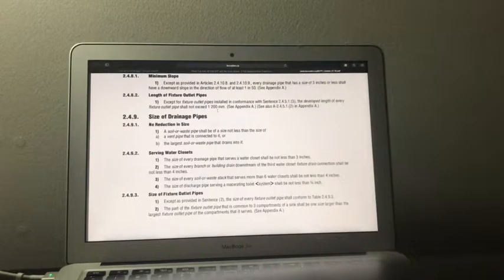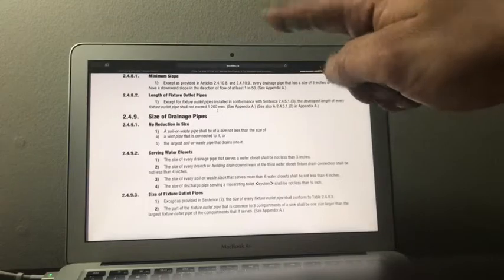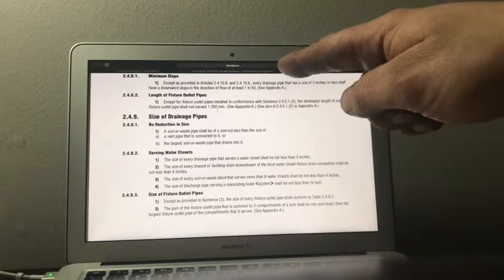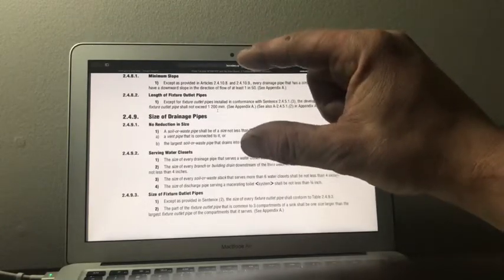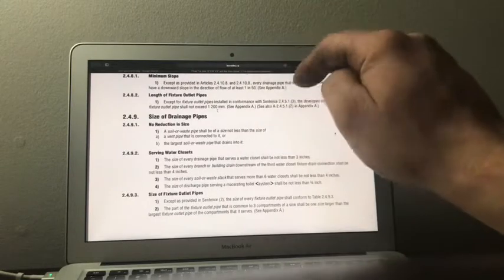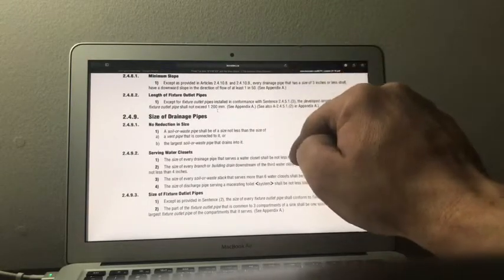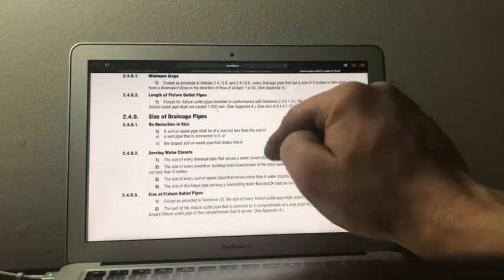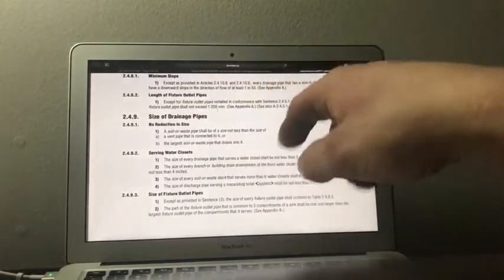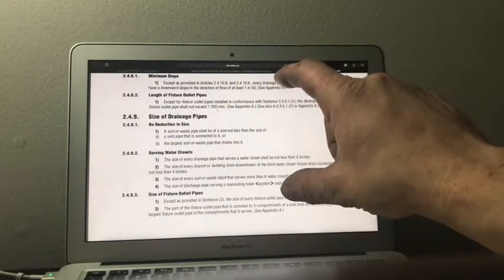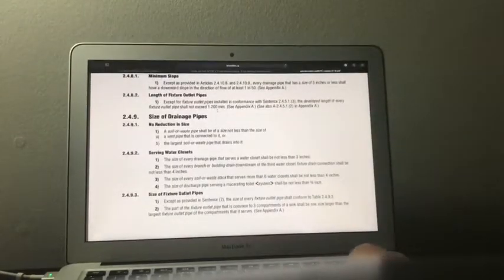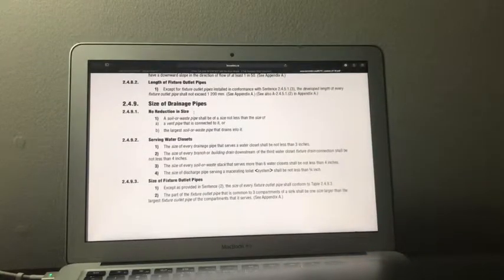So when it's dropping down in a hospital situation especially, sometimes you've got the tin guy pressed against the ceiling with his ducting. You've got a floor drain here, you're dropping down to get around him, putting on a P-trap. And you just got to make sure that this height isn't more than 1,200 millimeters. And no reduction in size.